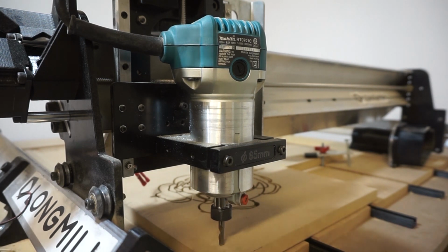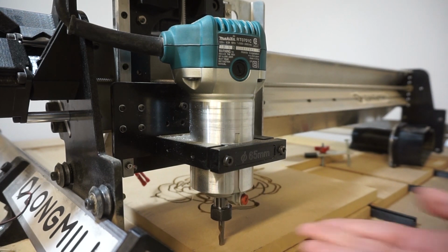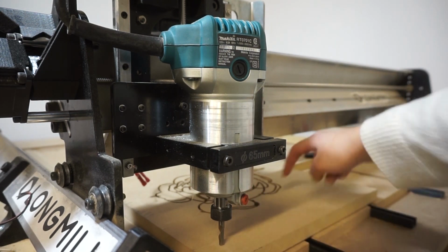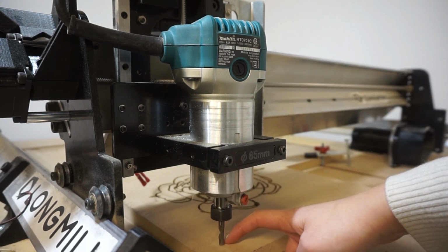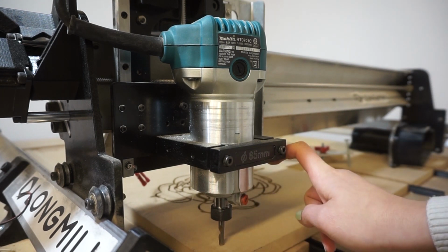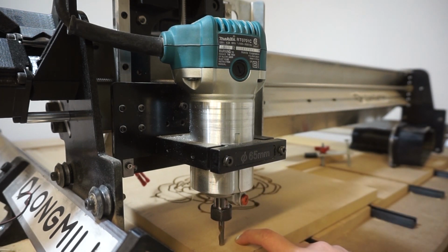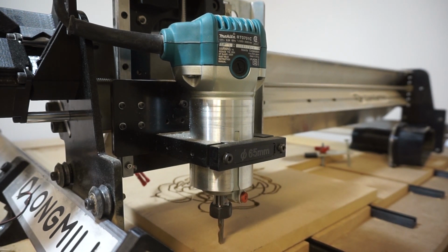All right, okay, you see what happened? It went all the way here to the XY coordinate and then it dropped to the Z. When I do return to 0, it returns to 0 for X, Y, and Z. So I should have just returned it to 0 for X and Y because the Z height changed because of the bit change. All right, well, it didn't break, so that's good.